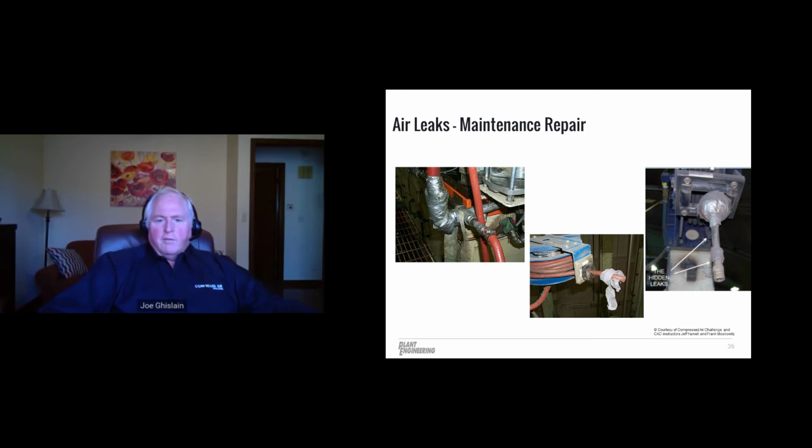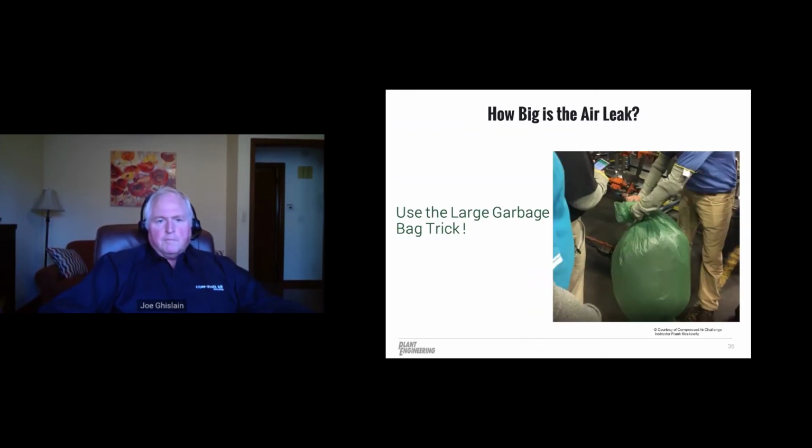So you have leaks that are going to be showing up, so you have to repair them properly as well when you're going through and doing it. And how big is the air leak? Well, with ultrasonic leak detectors, you can go through and do estimates. A lot of the companies give you software that tells you exactly what's happening, where it's at, what the location is, and an estimate on it.